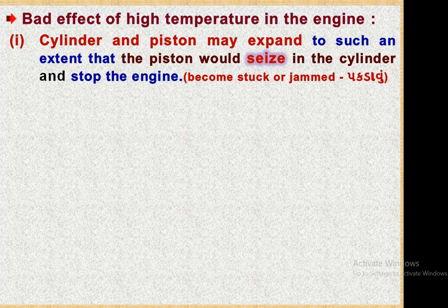So it is necessary to drop down the temperature of the piston to a certain degree so that its expansion will not be too much. If it expands more, it may come into close contact with the cylinder and seize in the cylinder, due to which the engine will stop.